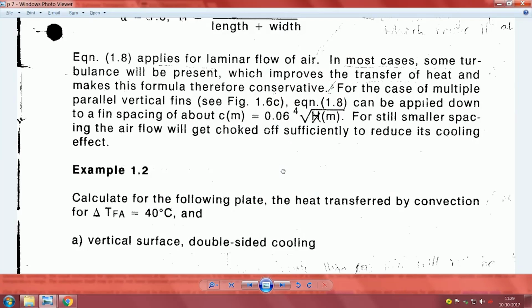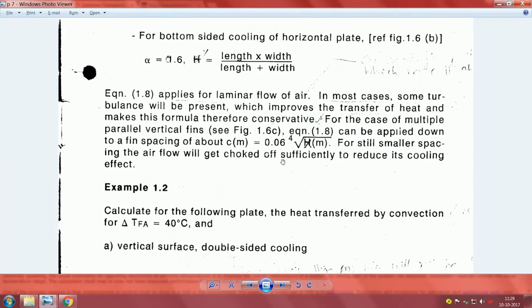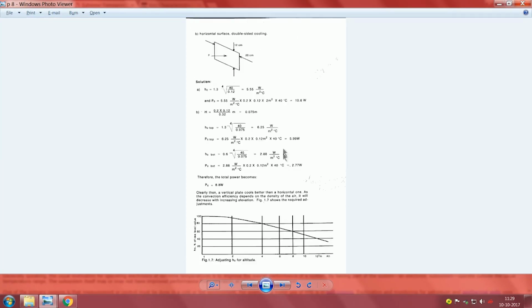So, if this were a plate, we have these fins which hold the plates together, two on the side top and then one in the middle, so that the spacing is maintained, and they were also made very thin, so that in the normal case they do not impede the airflow. Then what has been found out is that if you make them close, it really does not help.